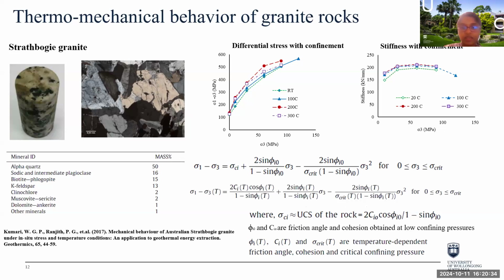We know traditionally rock failure in compression can occur in two main ways: dilatancy and failure by strain softening under relatively low confining pressures, and failure by strain hardening under elevated confining pressures. So this has some experimental evidence showing how rock failure alters with extreme confining pressures, with the transitional regime at intermediate pressures. We observed when specimens fail below 60 megapascal confining pressure, they mainly fail by shear localization. However, when samples were tested beyond 90 megapascal, they exhibited some strain hardening characteristics.